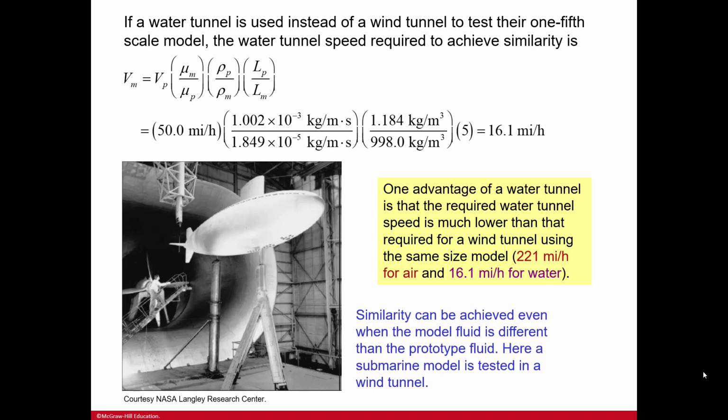Here, a submarine model is tested in a wind tunnel. Water tunnels are very expensive, right? They are costly to build, costly to maintain, costly to continue to fill, to test, just everything that goes along with it. So if you can adjust the numbers, adjust the velocities, adjust those things in a wind tunnel to test those items that would need to go in the water, then that's a great alternative,